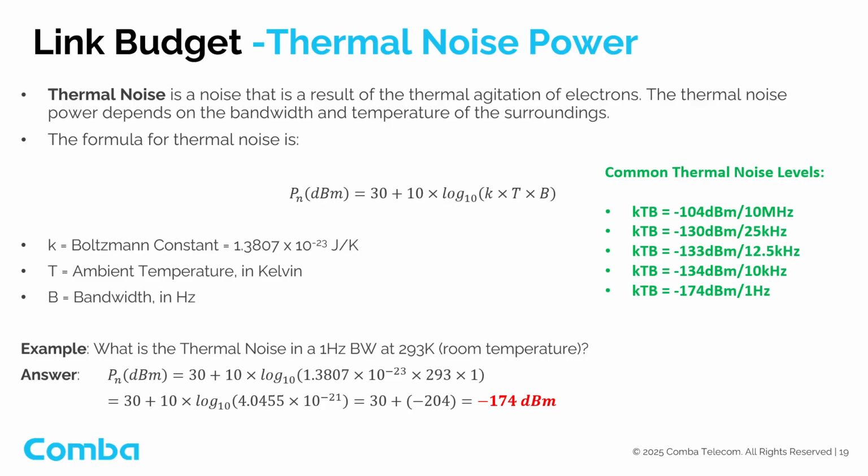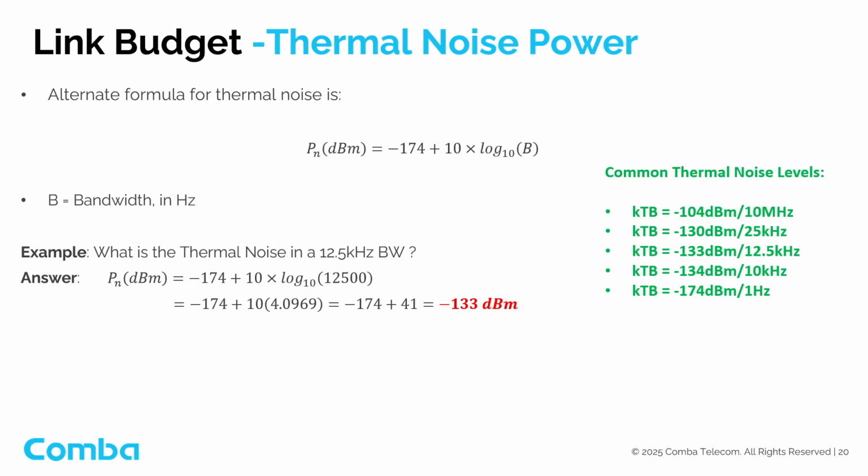Furthermore, there are thermal noise power calculators online which are available for free by performing a quick web search. Some of the most common thermal noise levels that we deal with when planning and designing public safety BDA systems are shown in green. It is recommended to memorize these thermal noise levels.